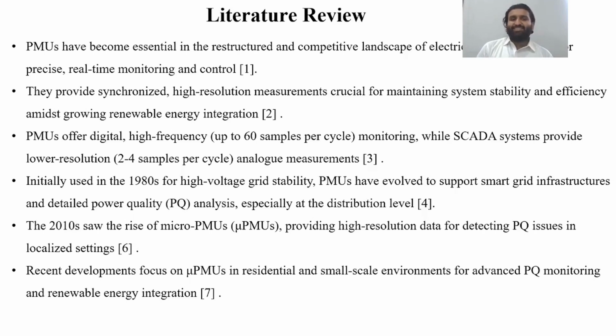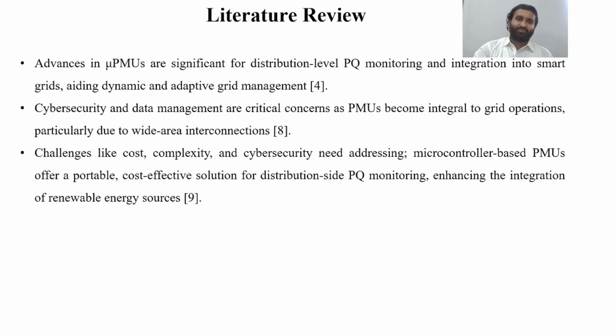In 2010, we saw the rise of micro PMUs, or microcontroller PMUs, providing high resolution data for detecting PQ issues in localized settings as well. Recent developments focus on micro PMUs in residential and small scale environments for advancing PQ monitoring and renewable energy integration. Advances in micro PMUs are significant for distribution level PQ monitoring and integration into smart grids, adding dynamic and adaptive grid measurements.